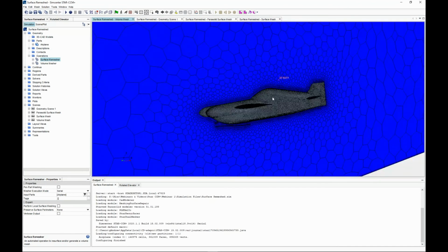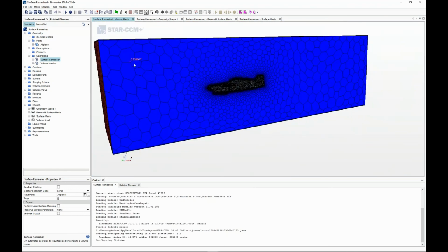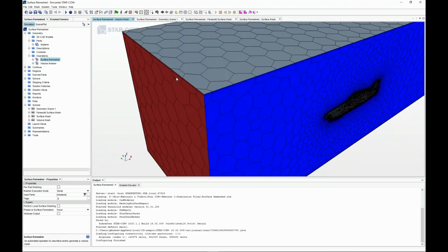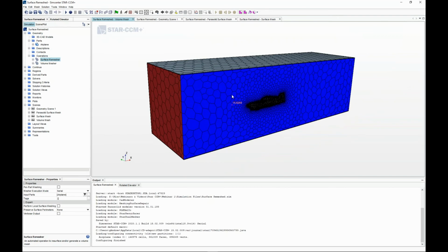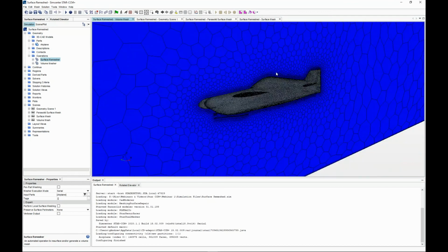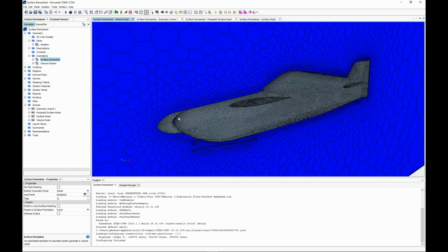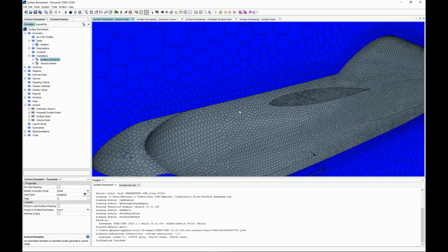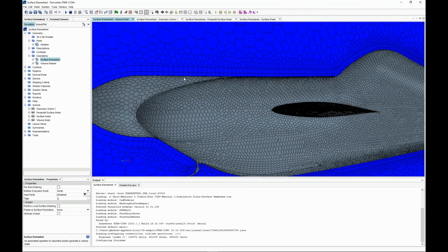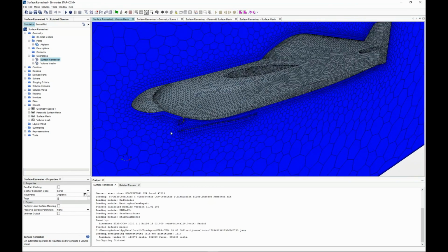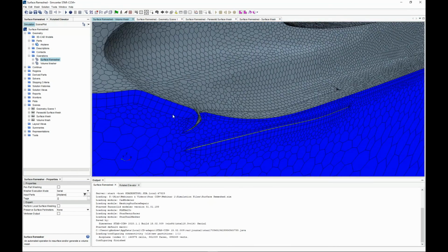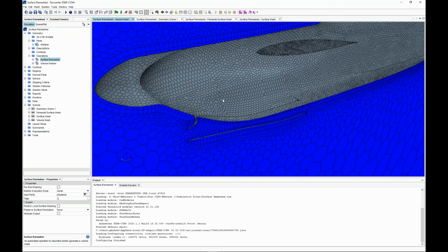If we look at it from the outside, you can almost see a cross section of the mesh. It's coarse where the gradients of different flow properties are small, and then it's fine where the gradients are high. And I've actually got a prism layer mesh turned on, which helps you refine boundary layer characteristics. Obviously, this is super thick. I would need to make this much more thin. The boundary layer obviously isn't that thick, especially up at the front. But that kind of gives you a sense. There's just so many different options for refining your mesh and capturing different phenomena.